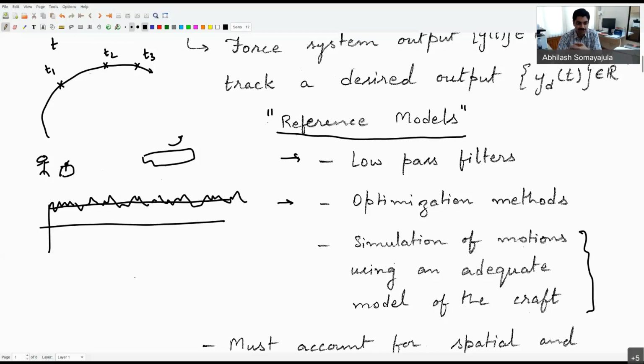What you give as a joystick input might have to be translated into a desired trajectory first, and then a control system at the back of it kicks in to track that desired trajectory. Okay, so in large scale, it creates a trajectory from the joystick. Correct.